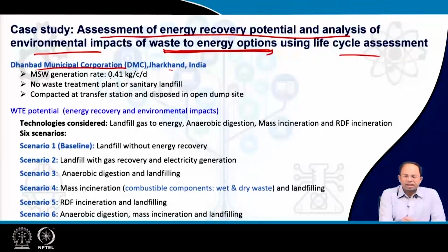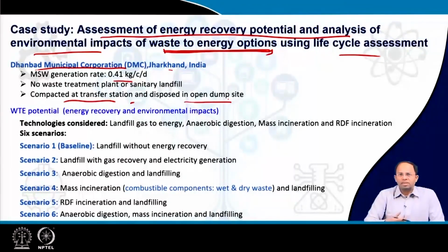The waste generation rate over here is around 0.41 kilograms per capita per day. And right now there is no waste treatment plant or sanitary landfill in this area. So waste is collected, compacted, taken to a transfer station, and eventually disposed to an open landfill site or open dump site. That is the situation now.